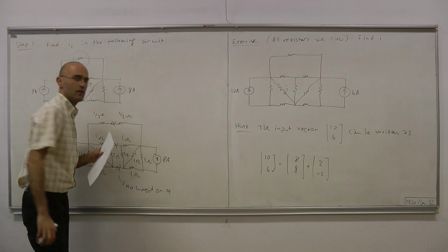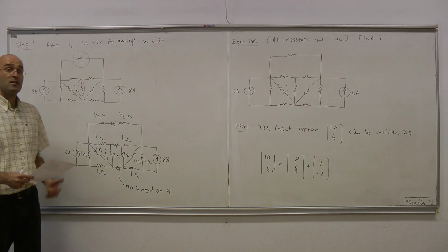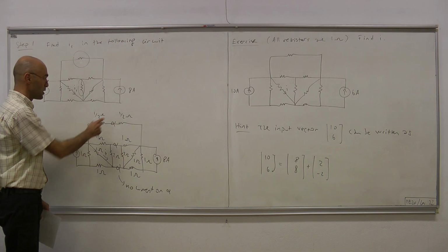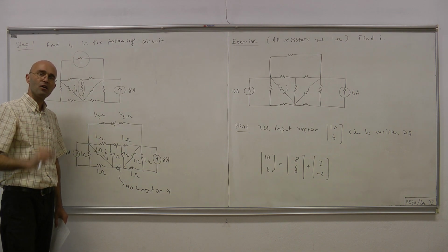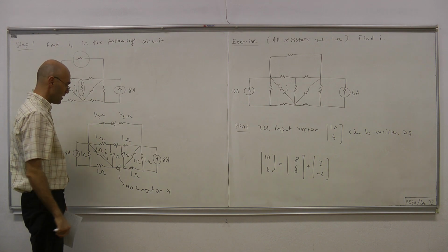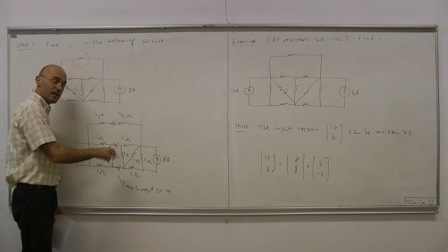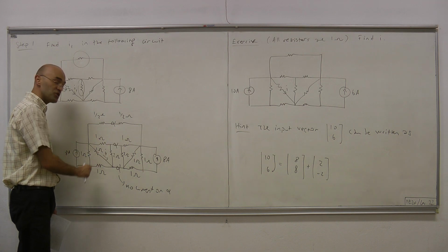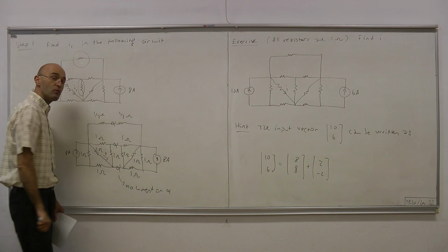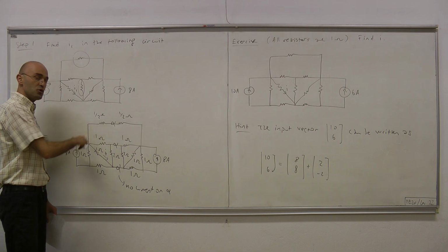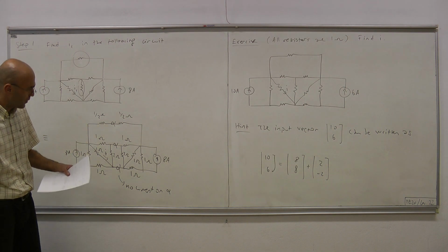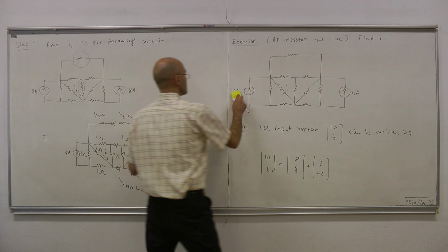on the wires. Okay. Since there is no current, we can replace those pieces of wires with open circuit, or we can take a pair of scissors and cut the circuit in half without affecting anything here. Okay, so I1 will still be the same if you cut those 3 wires, and if you do that, the circuit becomes much simpler. Okay, hence.